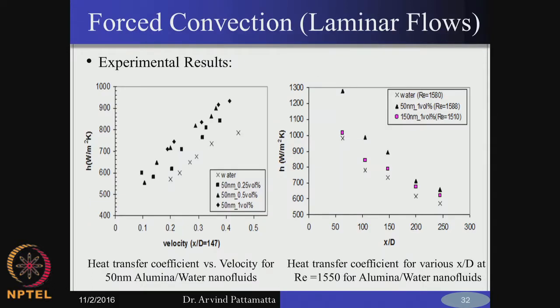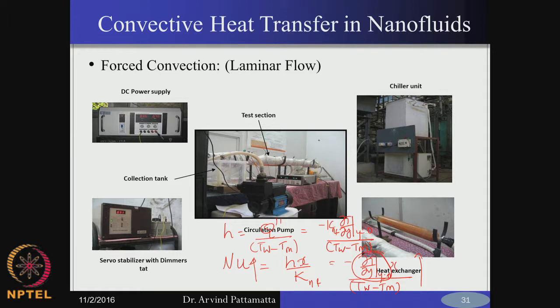So most of the literature mainly plots heat transfer coefficient, but of course when they are doing this, they sometimes have this problem where for the base fluid you use k of base fluid, and for the nano fluid you use k of nano fluid.